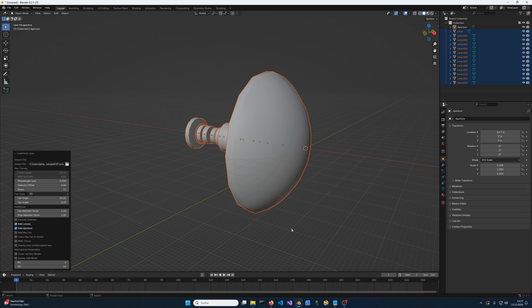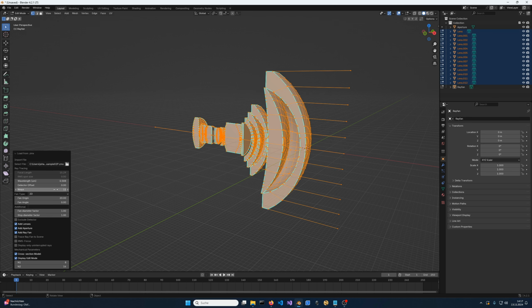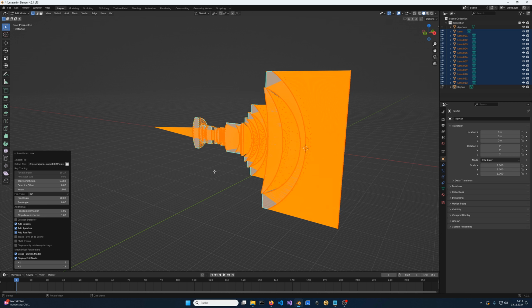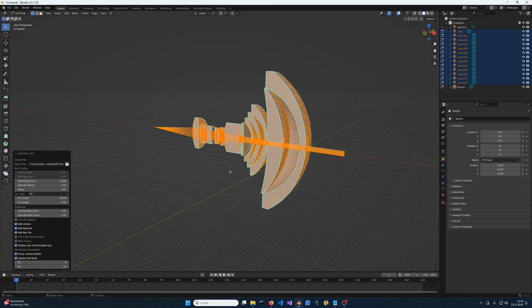Back in Blender, we can now go through a few lens designs and see what we can do and learn about them. I've again loaded the wide angle lens shown earlier with default settings here. So I will activate the ray fan with cross-section view, and increase the number of rays so that we get a good amount of rays passing through the lens. That's probably more than we need. With the 2D fan, we will display only the uninterrupted rays for now.